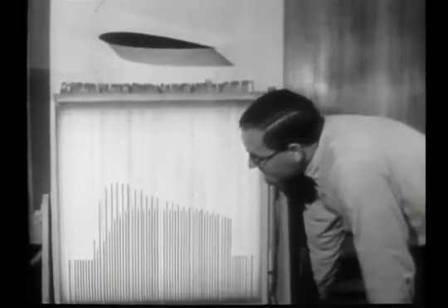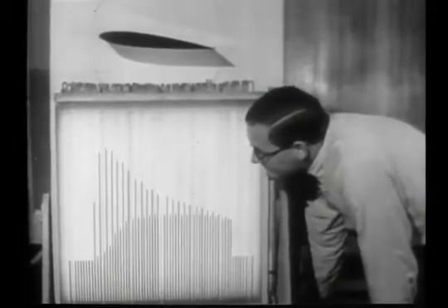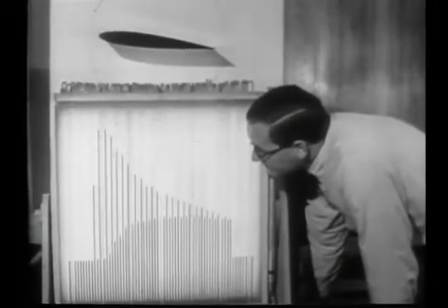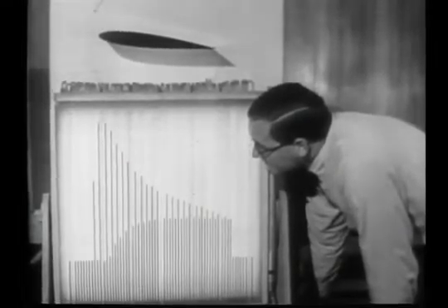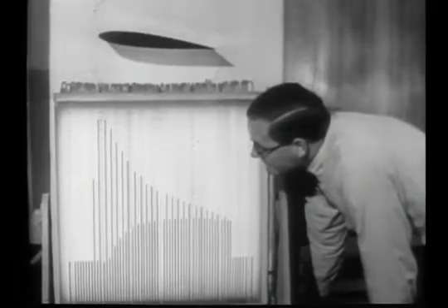Increasing the angle of attack destroys the symmetry of the distribution. The minimum pressure point becomes more pronounced and moves forward, increasing the severity of the adverse gradient.